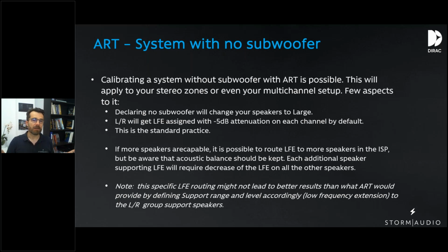Doing that, all speakers will play the LFE, and ART will align all of them, making sure that they support each other. And this is working very fine. We cannot guarantee that this is going to bring the best performance, but the most important thing is that if you want to do that, you need to make sure, of course, that your speakers can support the LFE frequencies.